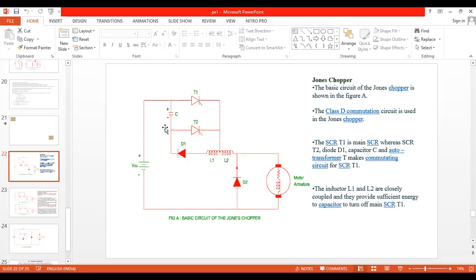So once again you have to draw the circuit, same circuit, and here the upper plate should be minus, the lower plate should be plus. So from L1 plus to D1, D1 to C plus to C minus, and from C minus to T1, T1 to L1 minus again. Okay, so this is case 3, which is not highlighted in many textbooks, this particular point, how the capacitor starts to recharge.